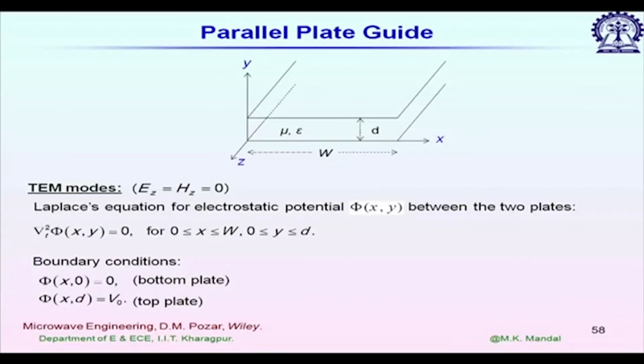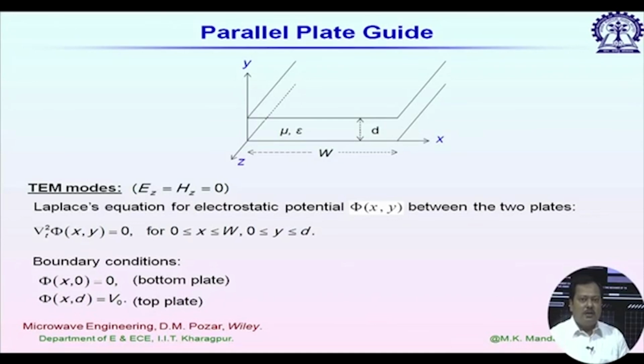Welcome back. Next we consider another scenario, we call it the parallel plate case. When we buy a substrate from the market, or printed circuit boards, another name is also laminate. It is basically a dielectric slab, and it comes with a top and bottom copper plane or copper cladding. So, this type of substrate with top and bottom metallization can also support surface wave modes, and in this